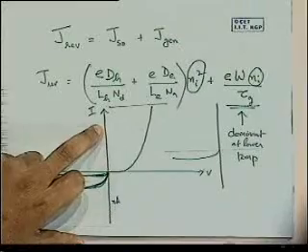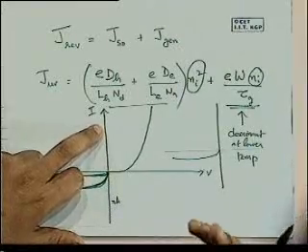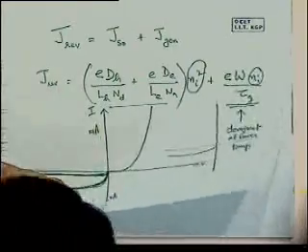And that's what makes Schottky diodes faster, because when you switch in various applications, you go from one direction to the other. It is the movement of majority carriers that is involved there, not minority carriers, which slow down the whole process. Charge storage, when it is going from one side to the other side, you're flipping back and forth in biasing. The Schottky diodes are much faster than the PN junctions because it does not involve minority carriers. There are other differences too. With PN junctions, you can usually go to much higher breakdown voltages and so on. There are pluses and minuses. But you have to recognize that the PN junction involves minority carriers, whereas the Schottky junction does not involve any minority carrier transport across the junction.